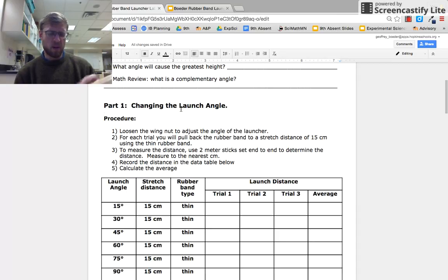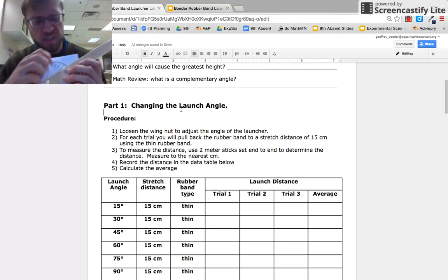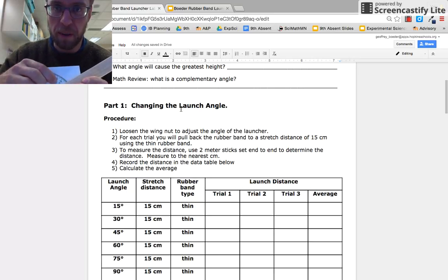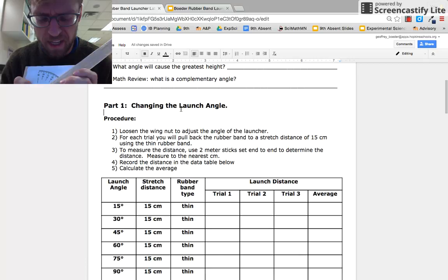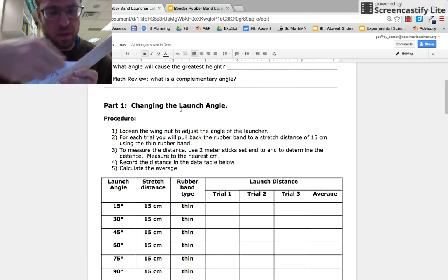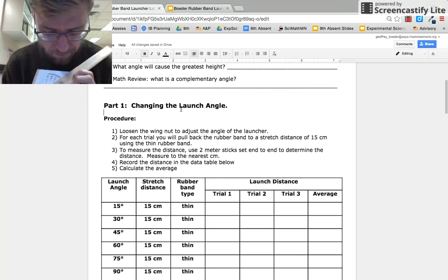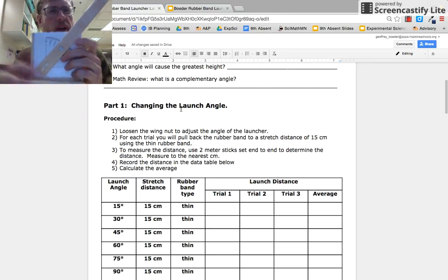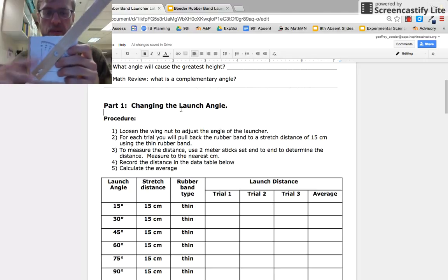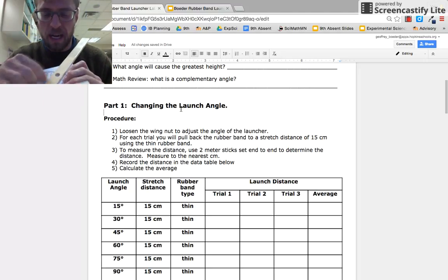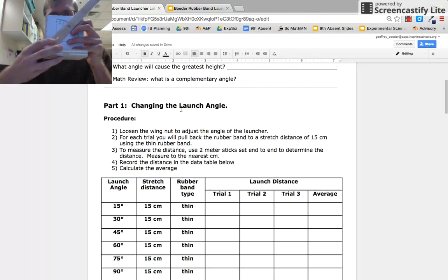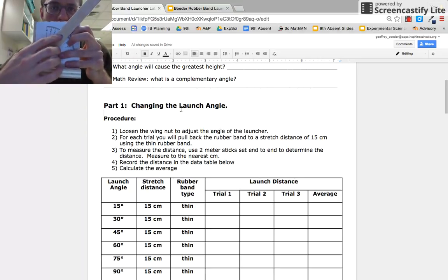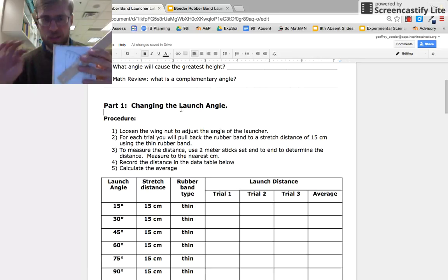Okay, let's say I want to put it right on the 50-degree line. So you'll see my protractor here has a 50-degree mark. Should I line up the top of this ruler with 50 degrees, or should I put the 50-degree mark right in the bullseye center of my viewfinder? That's right, in the center of the viewfinder. That's what you need to be measuring your angle with. Don't measure it with the top of the line here, because you'll notice your pivot point is in the center of the ruler here, so you need to be in the center of your viewfinder when you adjust your angle. Okay, just a little note about that.